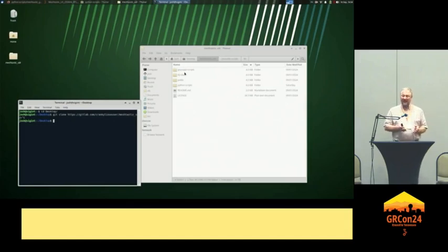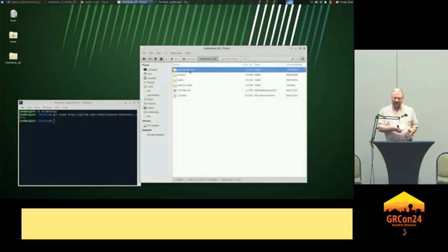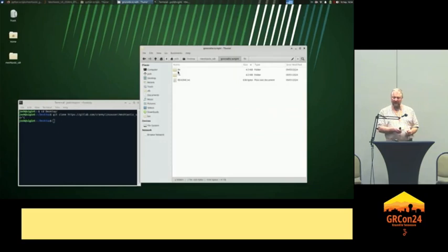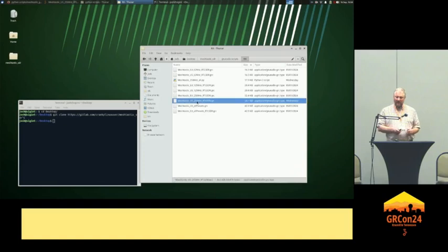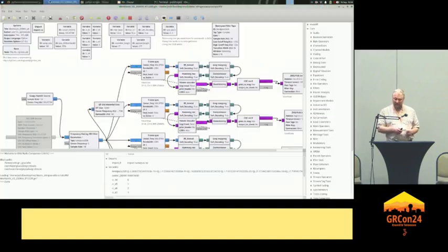The first one we're looking at is the GNU Radio directory, and that's where the scripts are for the receive and the transmit flows. They are different flows right now. Along with this, we also separate these out into the different frequencies: European is 868 megahertz, US is 902 to 928 megahertz. So I also separate that out for ease of use for the people who want to use this platform.